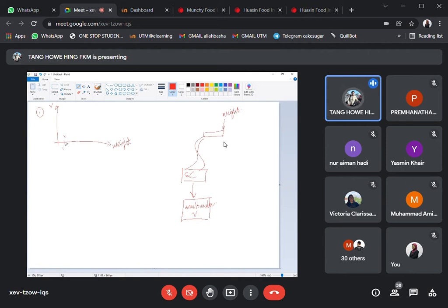You apply a weight, let's say 1 kilogram, and then 2 kilogram, or 1.5 kilogram, and so on, 3 kilogram. Let's say with 1 kilogram, 2 kilogram, and then 3 kilogram, you measure the voltage. Then later on 4 kilogram. So eventually you are going to get a straight line like this. Okay, so this is the first step. You want to get this graph. All right. The second step will be to establish the relationship.